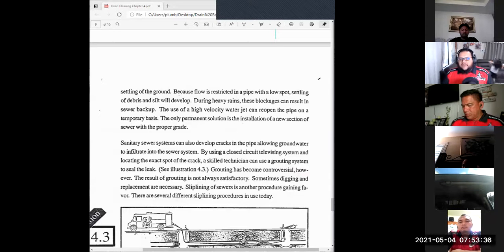You're not going to line a pipe that's bellied, because all you're doing is making the belly slicker. Yeah, maybe it'll work, maybe it won't, but it's not the way. You're still going to have that puddle in the pipe, and the potential of it building up. So whenever dealing with a belly, I would always recommend it has to be dug up and regraded, and that is the way to take away a belly.